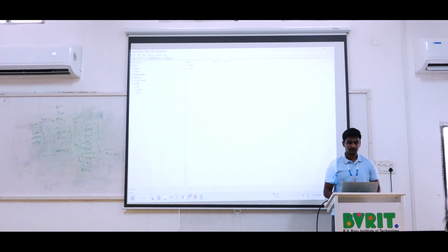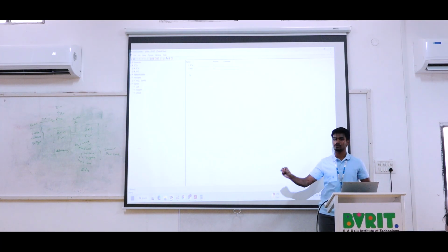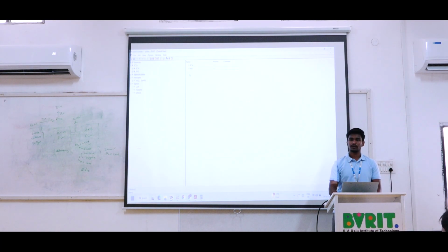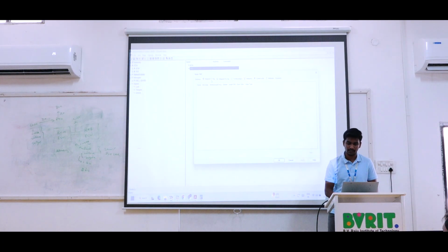Okay, so after completion of the messages, we go to the nodes. Now we need to set who is the transmitter and who is the receiver. As per our knowledge, the transmitter is RKE. So just open the RKE. We have different kinds of definitions: mapped TX signal, mapped RX signal, TX messages. So what are the signals mapping for the different directions?